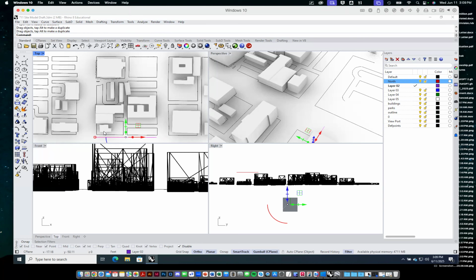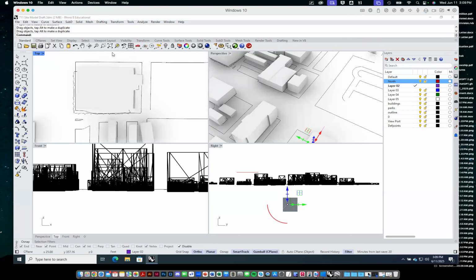We have 25-foot north-south increments for parcels. We have 140 feet, 20 feet of easement for the alleyway, then 140 feet for parcels. Simply map that out, superimpose it over this, start cleaning up. Because what you can see is that this is like some sort of weird machine vision tracing of a photograph of a satellite, and so all of these things are slightly off. Let's just clean them up. For our own purposes, it'll be much easier that way. Does that make sense?